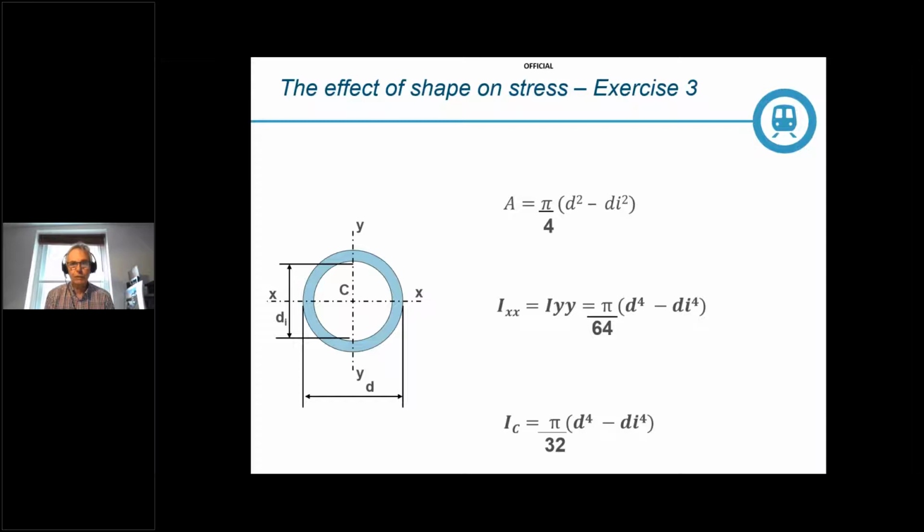If you then rolled that into a tube, you'd end up with a tube 250 millimeters diameter. If you work out the resisting strains on that, for a tube, we've used no more material, we've just turned it into a tube, so it's no heavier. It would actually be 11 times the resistance of the same material used as a solid bar.